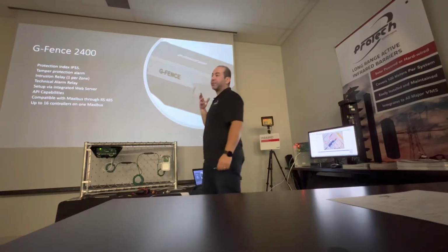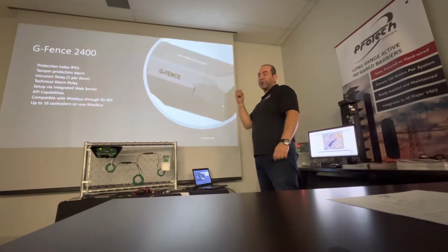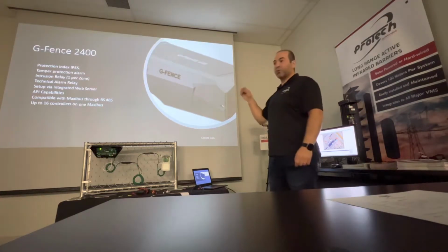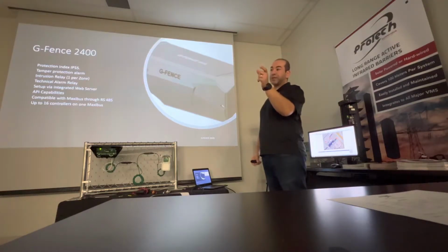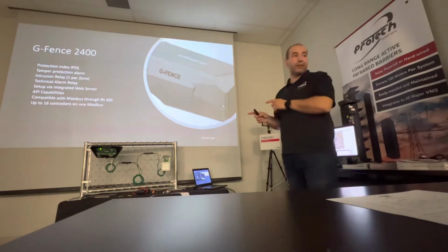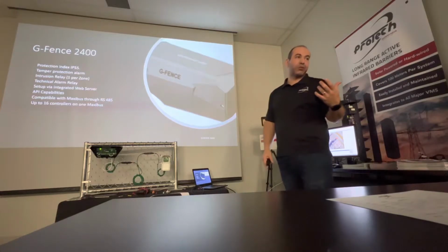You receive a technical alarm between sensor number 12 and 13, and it will be on zone number 2. So in the logs, you will see zone number 2 has been triggered, alarm, and you will see the sensor also. But if your system is tied to a VMS, you will not receive the sensor information, you receive the zone that has been triggered.